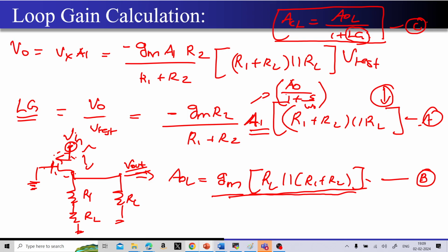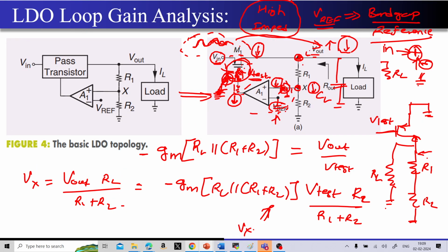Okay, I got where you are coming from. That's a good question. So basically the doubt entirely is what should be considered as the open loop and what should be considered as the feedback, right? This is your doubt, if I try to represent it in one statement. So now you can just break the loop. You can take this complete part as feedback, or you can take only a very small portion as feedback, or you can do any combination. The only thing is the final answer is not going to change.